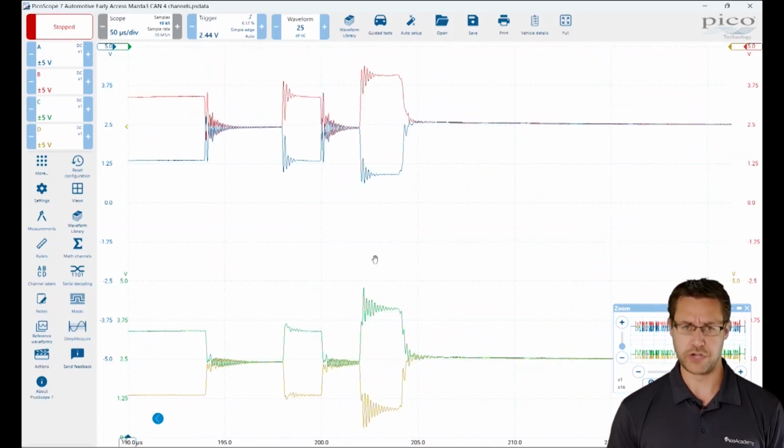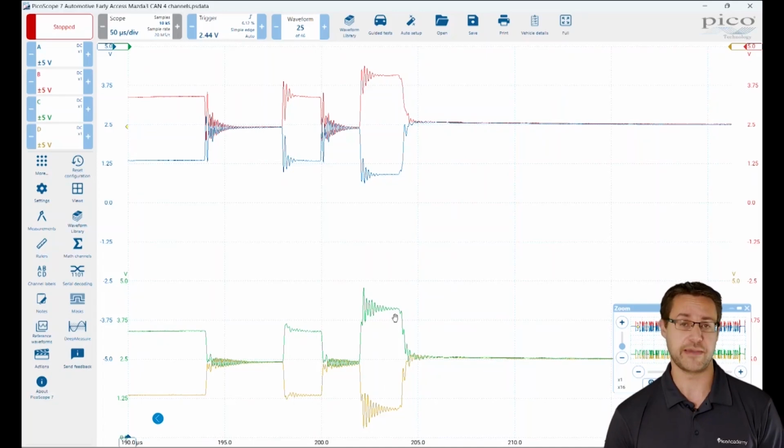Now we get lots of ringing. So why is there a difference between the two? Well, basically every ECU comes online at that point. Every ECU has to announce and acknowledge that they have received that message. In doing so, if there was a problem, in this case, we know what the issue is. There was a breakdown in the connection between the network.